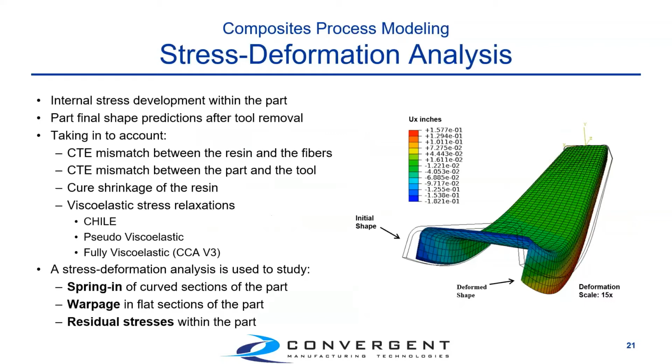In terms of representing the material stress evolution and modulus, there are different frameworks. There's the linear elastic, cure hardening instantaneously linear elastic, or CHILE approach, which for each step assumes that the resin behavior is linear elastic. Or you can go more advanced into pseudo viscoelastic or full viscoelastic representation of the material behavior, depending on the cure cycle, if the material devitrifies during the cure cycle or how complex the cycle is. You can choose the right type of simulation.